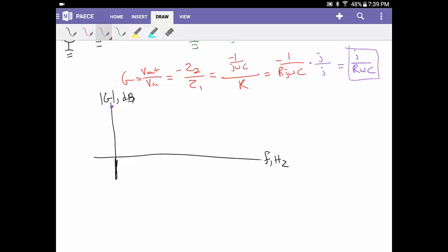and you may look at this and say, okay, well, it looks like a linear relationship. If I increase omega more and more, my terms should start getting smaller and smaller. There are no squared terms or anything like that. So our gain will look something like this. And on the web page that I provided you in the sample circuits, in every circuit, you can see this happen. And you might say, oh, well, at the really low bands or the really high bands, it curves off. That's because this simulation takes into account that these op-amps are not perfect.